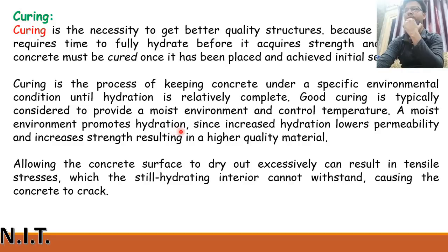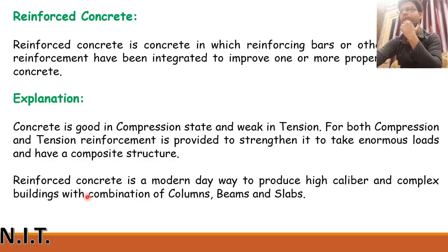A moist environment promotes hydration, since increased hydration lowers permeability and increases strength, resulting in a higher quality material. Allowing the concrete surface to dry out excessively can result in tensile stresses. If the concrete surface dries out excessively after pouring, what will happen? It will result in a build-up of tensile stresses, which the still-hydrating interior cannot withstand, causing the concrete to crack. That's why curing is most important for every project.